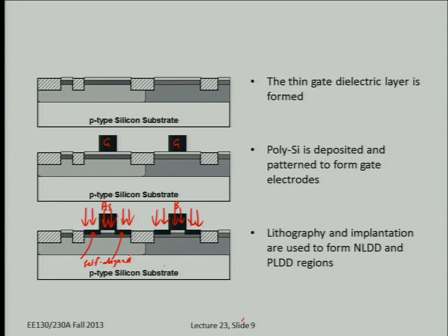Yes, Pera. Okay, so the question is, how do the implanted dopants affect the gate material? So remember, for an NMOS device, if we have a polycrystalline silicon gate material, what is typically the dopant type? Yes, so for NMOS, we have an N+ gate. For PMOS, we have a P+ gate. So actually, the implants also dope the gate, N-type or P-type. But they also prevent the dopants from getting into the silicon, so you can form a self-aligned channel.